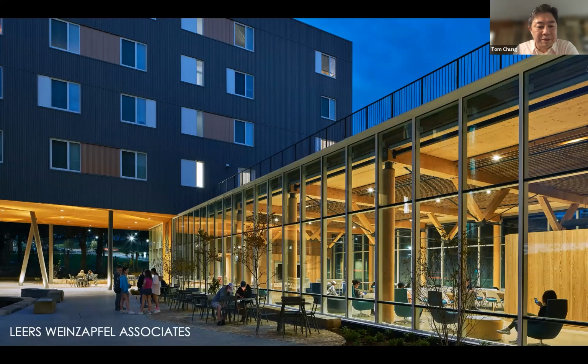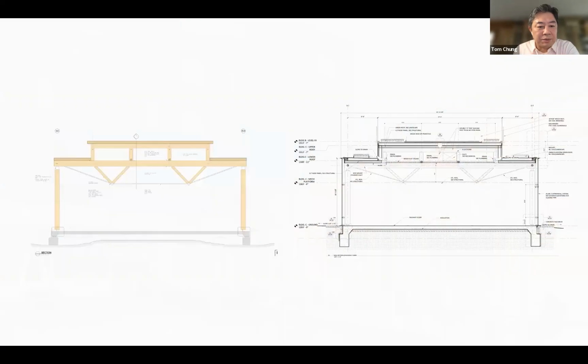And as I end this case study, just to focus on the project's main central space, this is called the cabin. This is the main community room. And this was the largest spanning space of the project. And so we used a simple truss geometry for material efficiency. It also had an elevated roof with a roof garden on top, so that we had to accommodate between the height and the level of the rooftop as well as the level of the overall ceiling, and came up with this queen post truss geometry to efficiently accommodate those two levels.